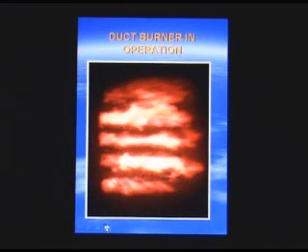Example of a combustion process through one of the viewports. The main issue with these is you need to ensure that the flame length is less than where the tubes are, obviously, since you don't want to have direct flame impingement, which will destroy the tubes.